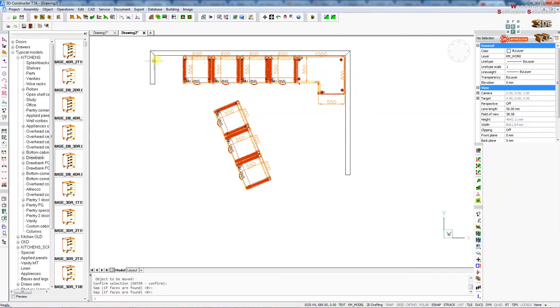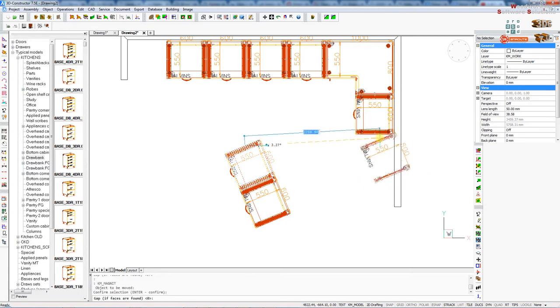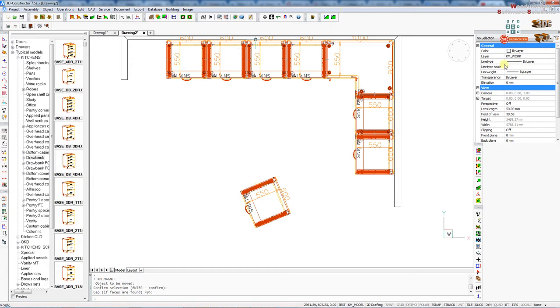Using the part operation. Let me show you how to use the part operation on a sample of cutting, manipulating or changing the benchtop. Let's say I don't need these cabinets in the middle, so I'm going to use these cabinets to extend my base cabinet line. This cabinet is extra, we'll delete it.